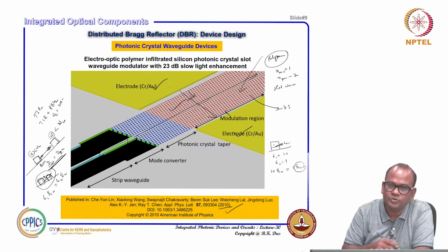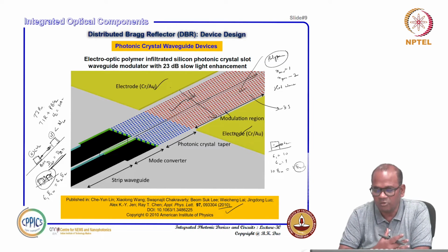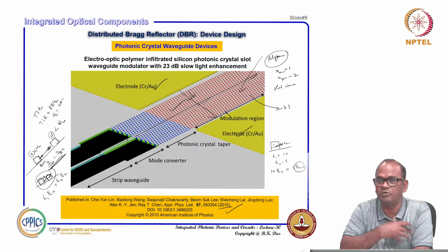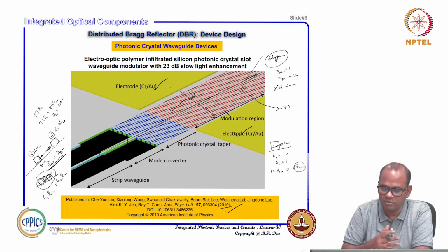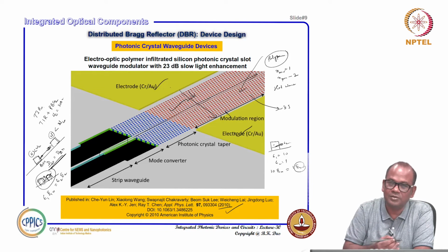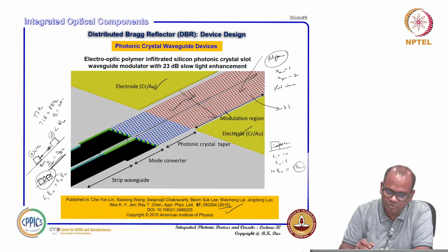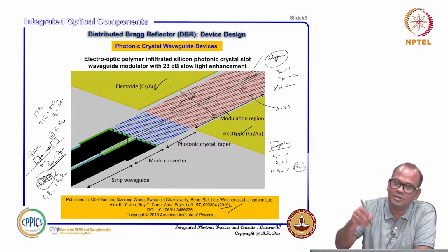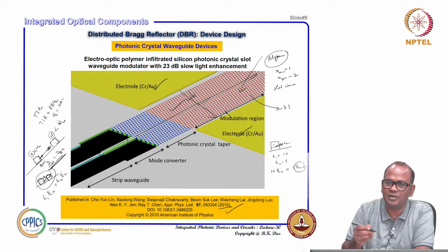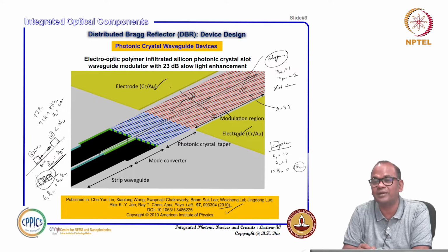Later on, in this direction, theoretically it is very good. If you have very good fabrication technology, you can get a good periodic structure with smooth sidewalls, and then a very low loss device. But typically, with so many periodic holes and holes in the sidewall, there will be roughness, and that is why photonic crystal waveguides are lossy in practice.